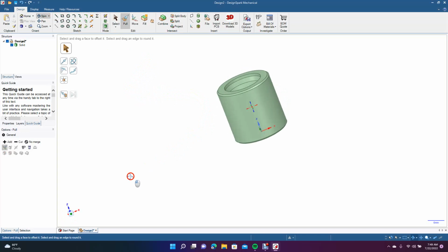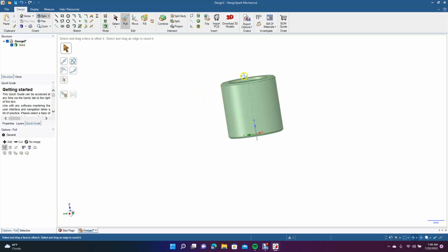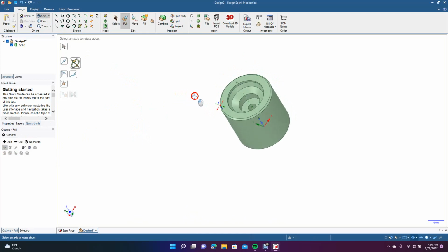So basically we created that cylinder. Select this green line here, hit K to split the cylinder in half, and then we did the plan view to straighten everything. We added our shape, did a revolve, but we did a revolve using the cut feature. So that's going to remove material. So we remove the inside of the material here, and now we have our skateboard wheel.